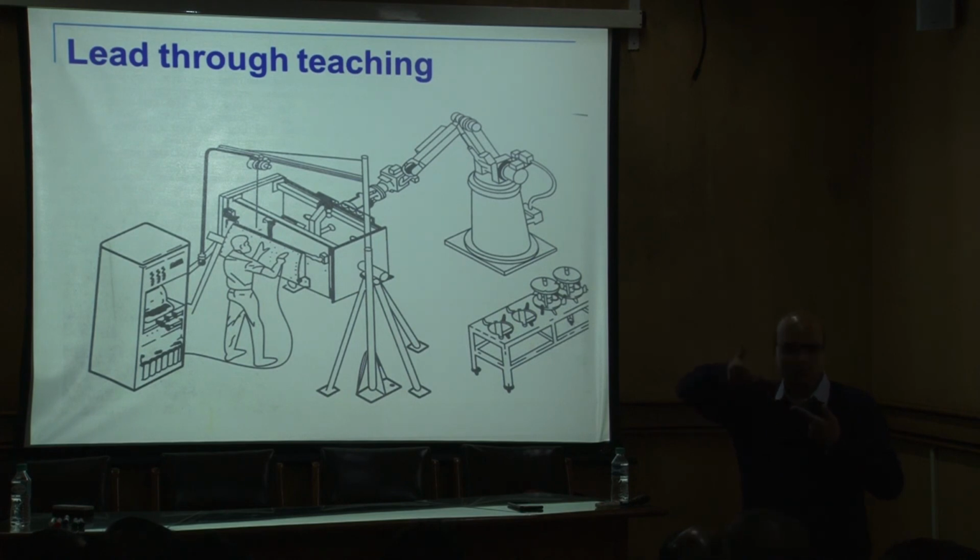Try and rotate clockwise, it will jump. You have to rotate anti-clockwise. If you see very carefully what this fellow is doing, he will not insert the nut and turn like this, he will turn on the other side. The moment you do anti-clockwise, the two threads will fall into place. Then clockwise.